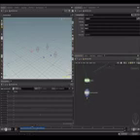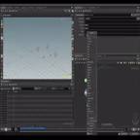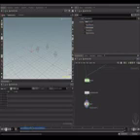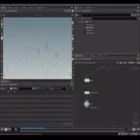So basically, we have to delete everything but collisions between object ID 2 and other object ID 1. So let's simply add a blast node, and let's write parameter other object ID equals 1. Let's select it and set it to points. And here we go. We are only getting these collisions.